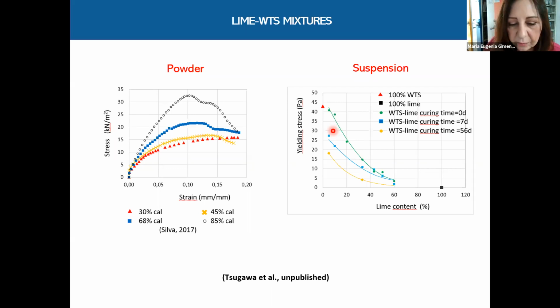of a dry material. That is why we looked for another material, a waste, to be incorporated to WTS with the same drying effect, and that was rock powder. However, as always in research, there are surprises, and there are significant differences regarding compaction parameters and the range of shear strength comparing lime sludge mixtures and rock powder sludge mixtures.